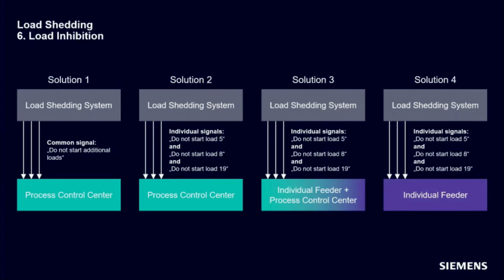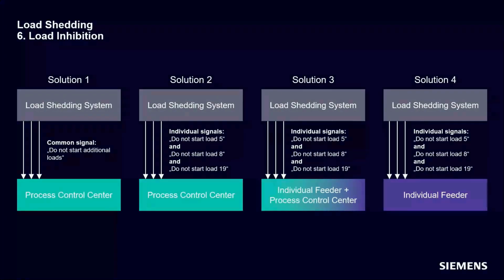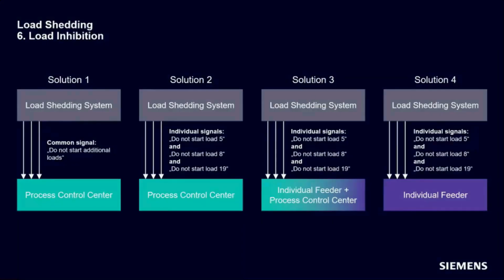To understand this function, you have to keep in mind that motors usually require much more power during the starting process, but during this period, the cos phi is reduced to around 0.2. This also means that most of this power increase is related to reactive power.